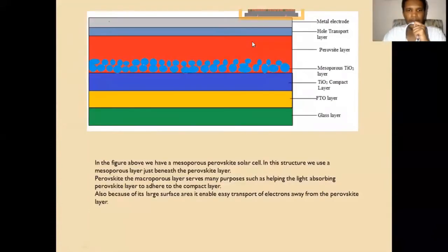We shall deposit this layer using the sol-gel method, specifically dip coating, where the substrate is periodically dipped into a precursor solution, creating a film, which you can see here on the surface of the substrate. This film shall then be dried and become a coating or a thin film.